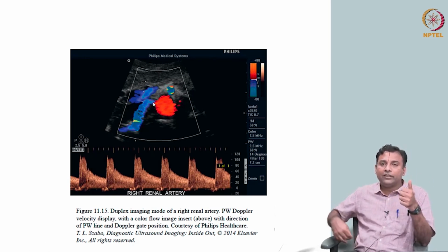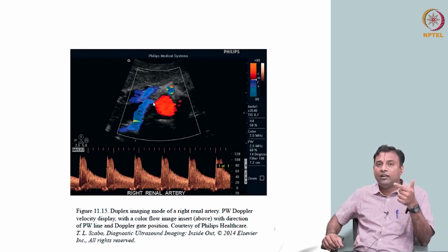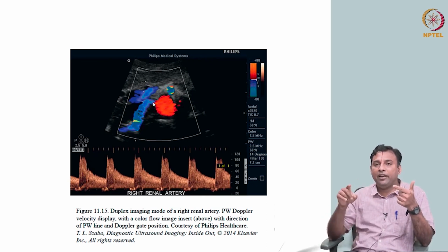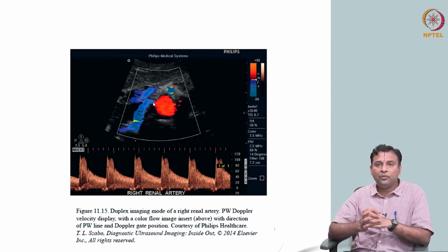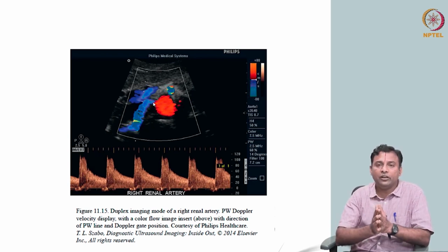So the take home message for the last part is your beam forming time delay profile. How do you design the time delay to accomplish focusing and steering, and the idea of incorporating apodization and doing this focusing, also dynamic receive focusing. I think if you get a hang of this, this is a good point to stop the introductory material.